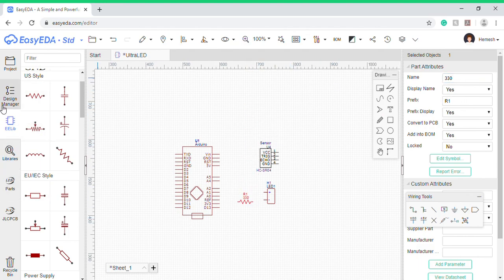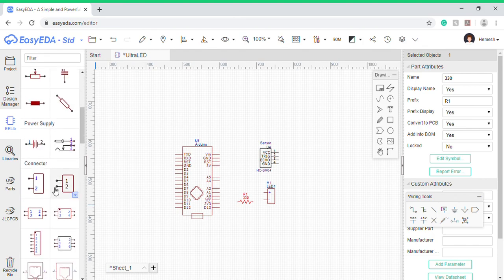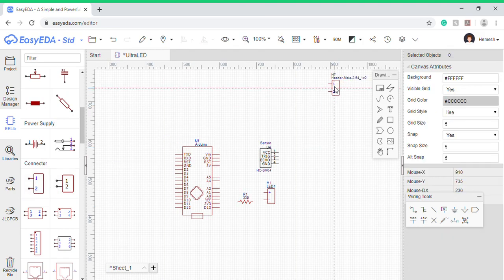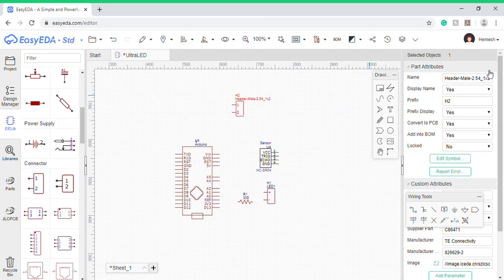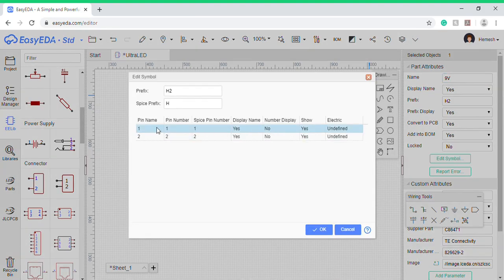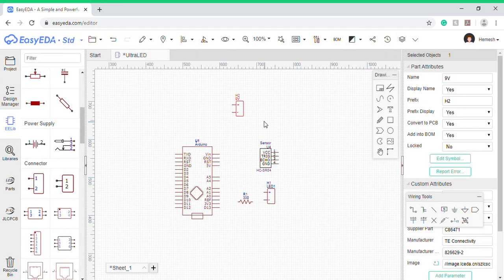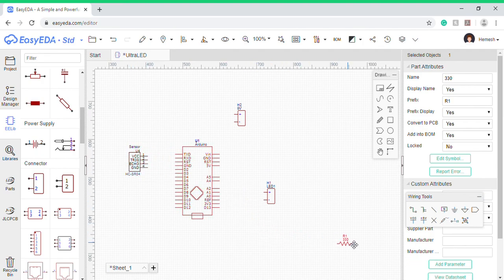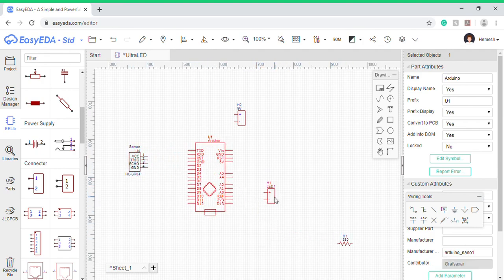And then we need the 9-volt battery power supply. We can directly connect the barrel jack if we want, but we'll connect it via headers to the VIN input. That's mostly preferred over this. So again, we'll take the male header and then name it 9 volt, and I'll edit the symbol too. I'll edit the symbol and then, as you can see, yeah, it got edited. So all our required components are added into the PCB and we just need to arrange them accordingly.